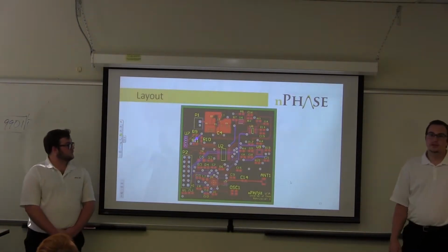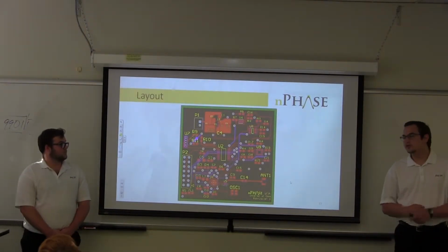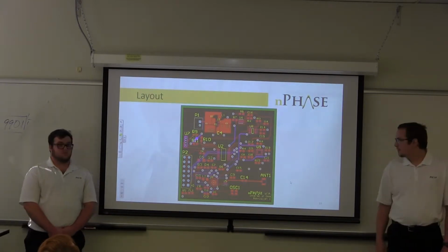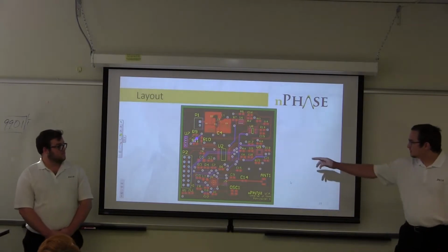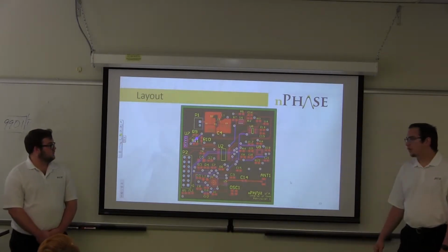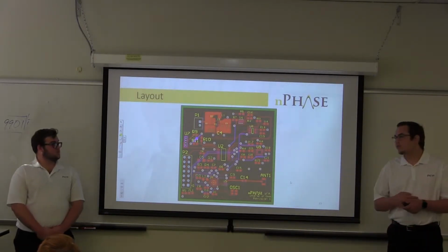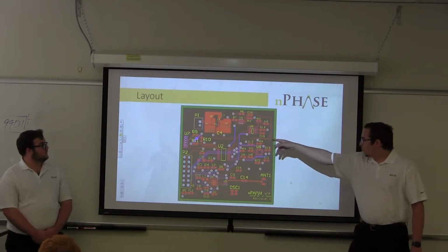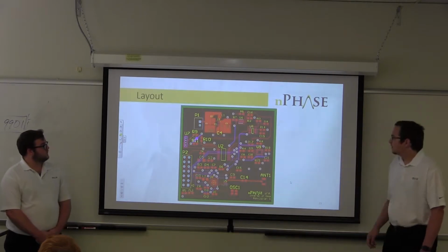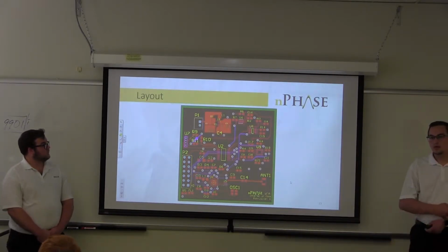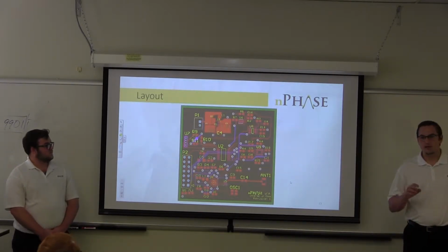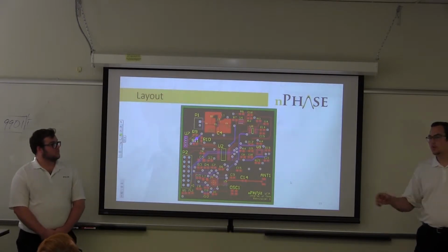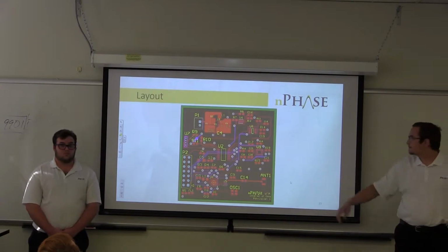This is a 2-inch by 2-inch layout. Most components, the resistors and capacitors, are 0603, unless otherwise stated. C5 is actually a polarized capacitor, which is a 3216 footprint. As well as if you look up here, U1, where all this is, that is the exact way you have to lay it out, because the voltage regulator cannot use traces to properly work on your board, so we had to match that exactly in the layout.